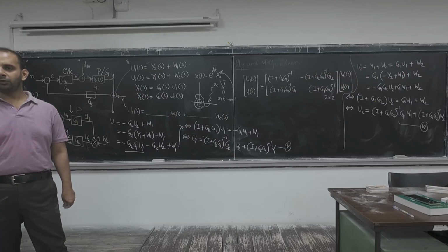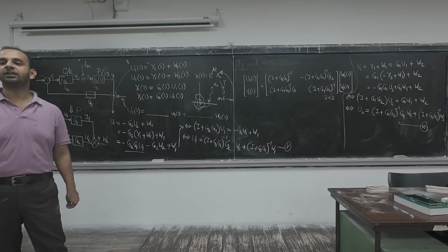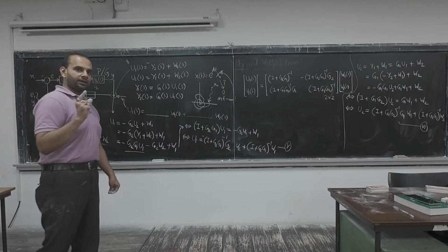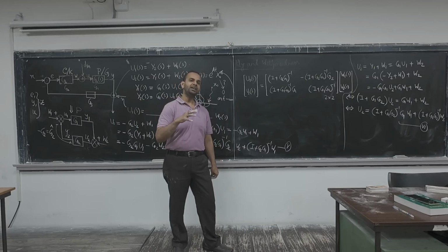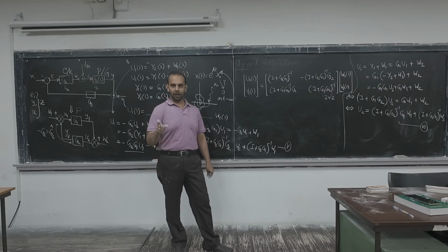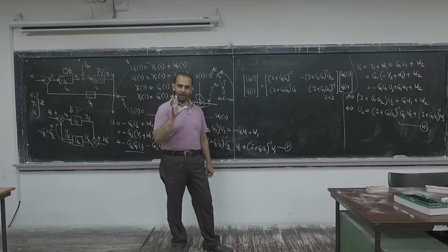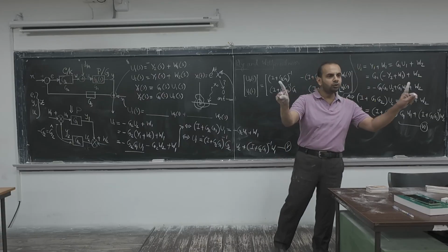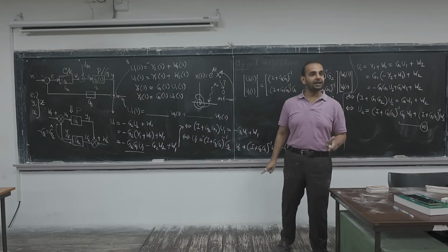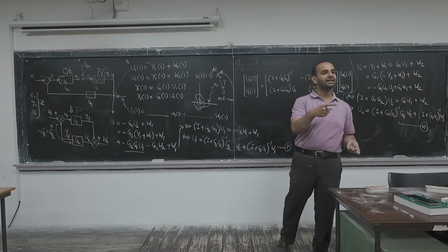So if we think only about BIBO stability, then if there is an unstable pole zero cancellation, internally there is a big massacre, but we are not taking care of that. That's why there is the internal stability concept, or even asymptotic stability, that gives more insight than BIBO stability. I hope all of you will agree with that. Why? Because BIBO stability is defined only with respect to the input-output connection. But asymptotic stability checks the behavior of the internal states as well.